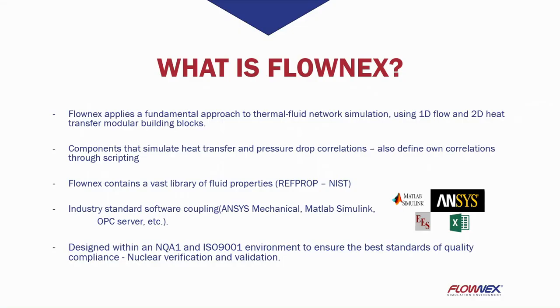Before we begin about the details regarding sCO2 modeling, I'd like to give you a brief overview of the FlowNEX software. FlowNEX applies a fundamental approach to thermal fluid network simulation using 1D flow and 2D heat transfer modular building blocks. FlowNEX contains components that simulate heat transfer and pressure drop correlations, and the user is also able to define their own correlation through FlowNEX's user-friendly scripting. FlowNEX contains a vast library of fluid properties obtained from RefProp and industry-standard software coupling, which is not limited to but includes ANSYS Mechanical, MATLAB Simulink, OPC Server, Excel, etc.